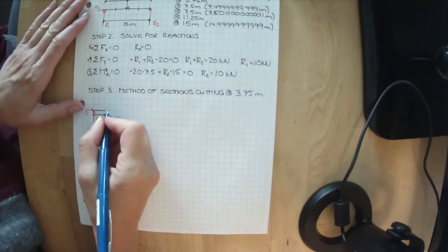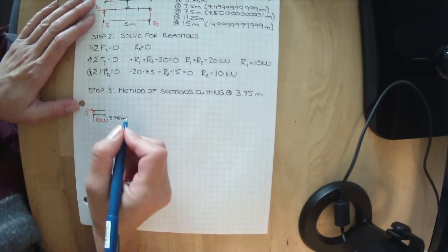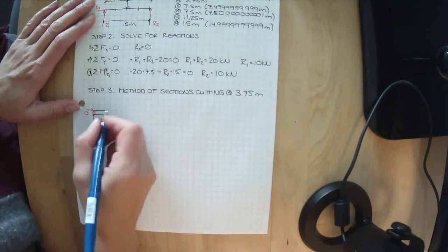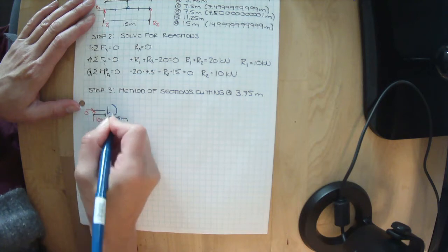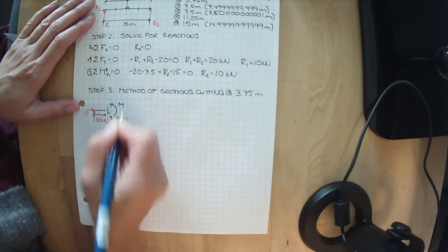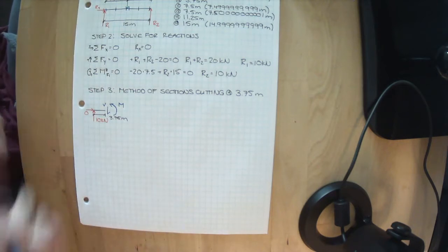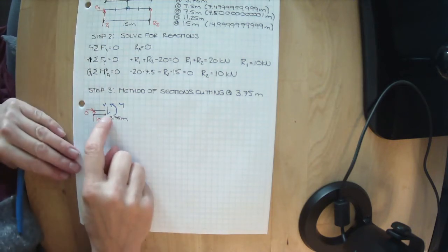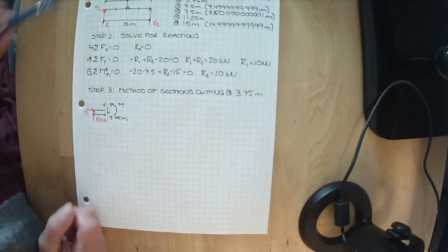So I am going to draw the internal shear and moment placeholders that we don't know what they are, that we can solve to see what is keeping this in static equilibrium. I'm going to say I have an unknown M and an unknown V. Now, you see I drew my arrow for shear with only half of the head on it?